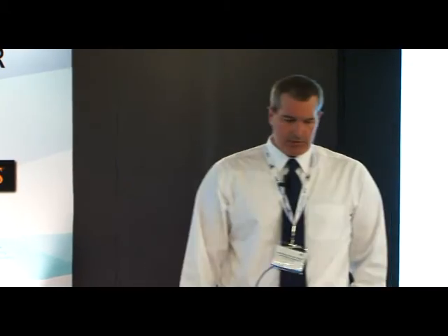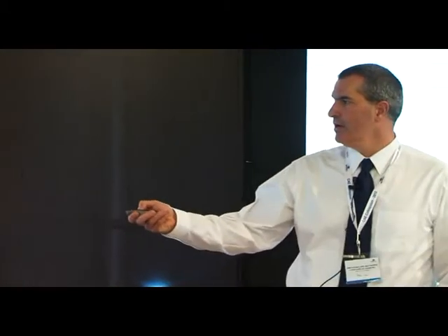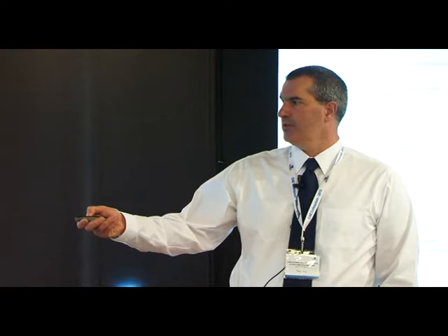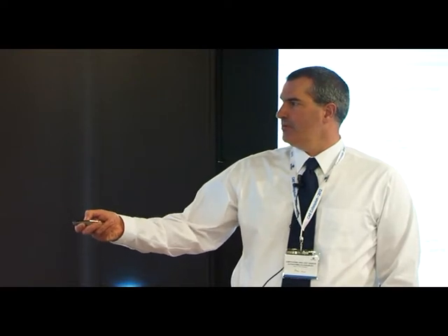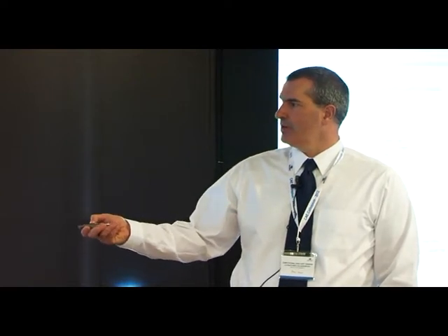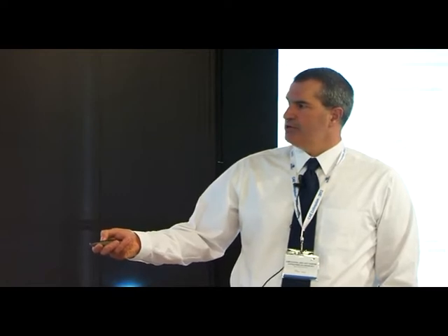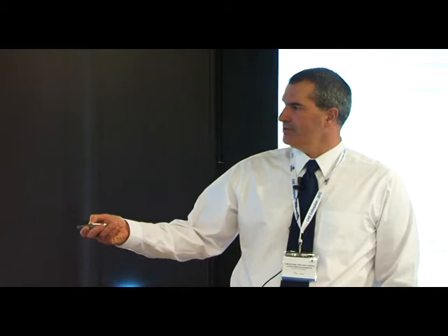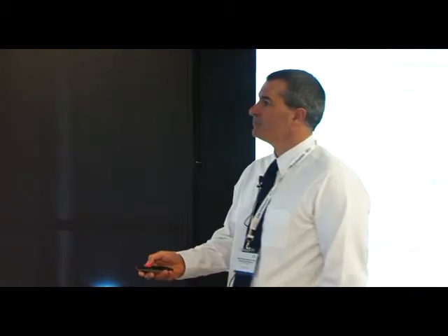So this is what our model looked like. Starting from the cross section up here, there was a high pressure vane here. Flow comes from the combustor simulator up here. This is the rotating component, which is these three blades here. And we modeled it with the leading edge impingement chamber in there and all of these film holes. You can see that here in these details. And then we included some of the aft film rows as well.